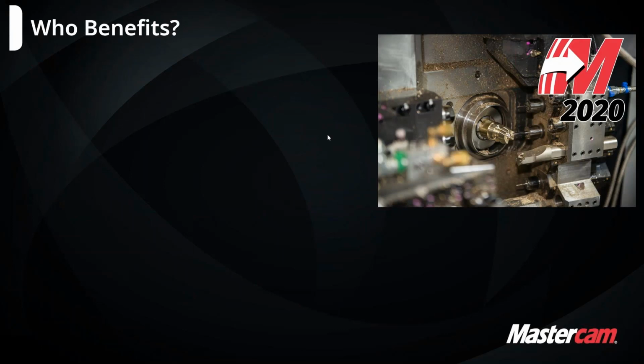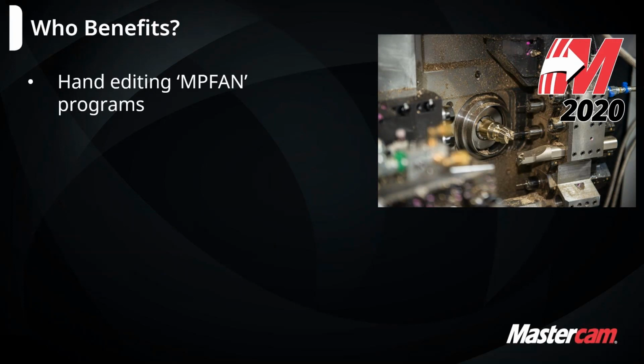So what are the benefits to this current solution that we're offering inside of Mastercam? The first is obviously if you're either manually programming or hand editing MP FANUC or MPL FANUC programs. So you're just taking a generic FANUC program out of Mastercam Lathe and then adding in all of the additional codes that the Swiss may need, or splitting the program up into the 3 code streams that the machine needs, or 2 depending on the piece of equipment.